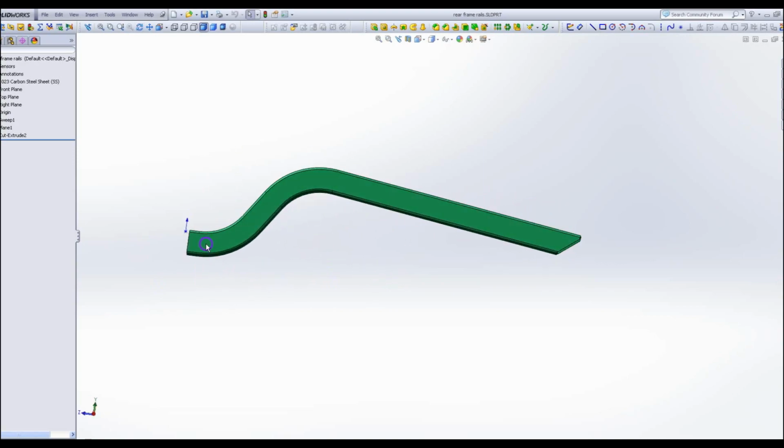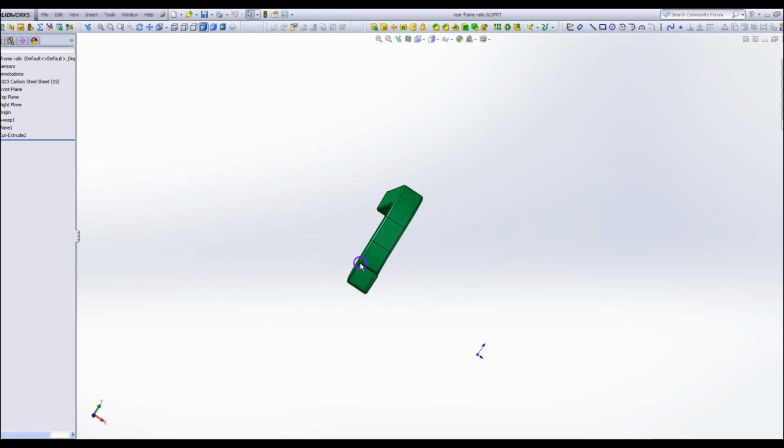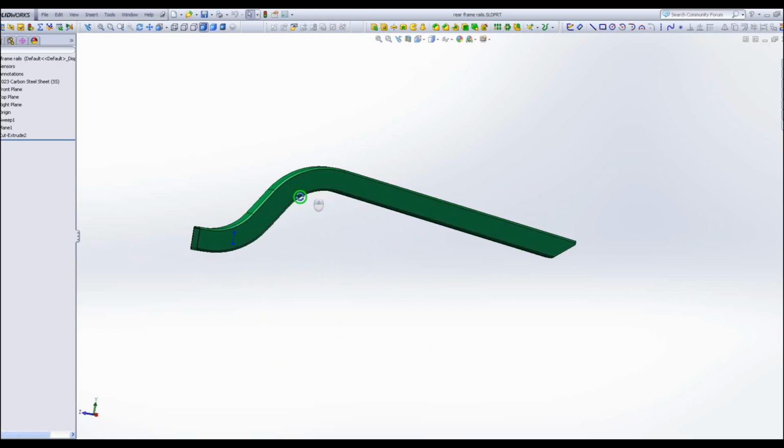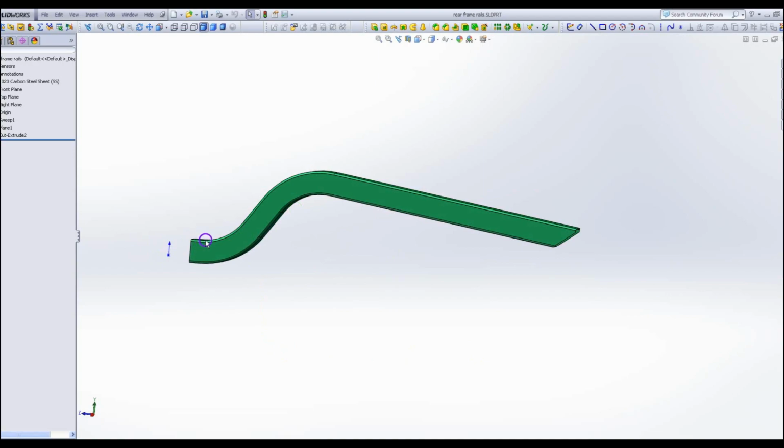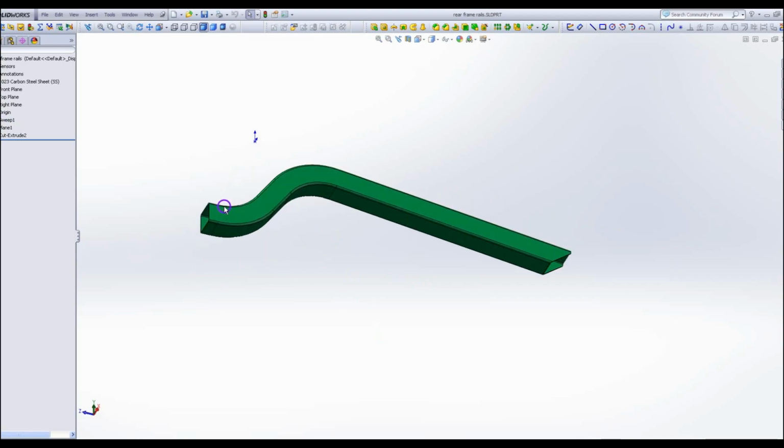So what I'm going to do is take some 1/8-inch plate with some flanges here and here, and then bend that to the contour of the existing trunk. So now I'll have a piece of, I don't know, 3/4 inch wide, 1/8-inch plate. It's pretty easily bendable into this shape. And then I will use that as a pattern to make this flat plate here, this side. And then I'll have to make 4 of those and 4 of those and weld those together.